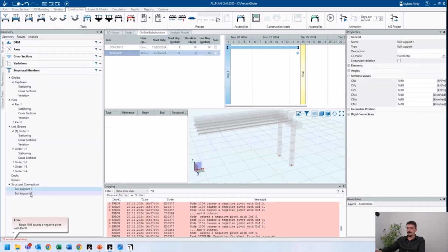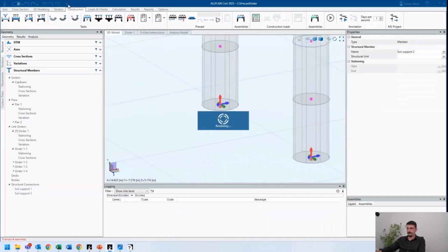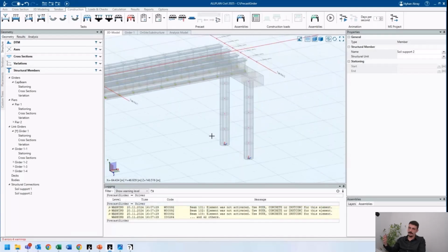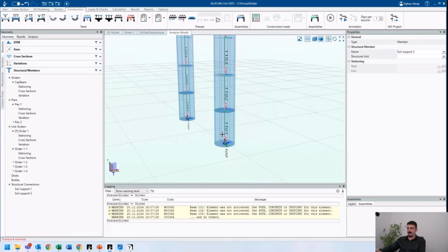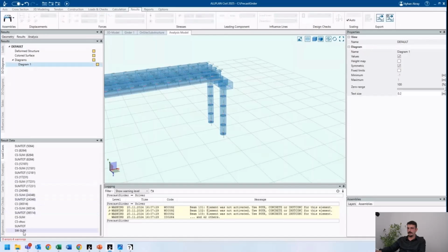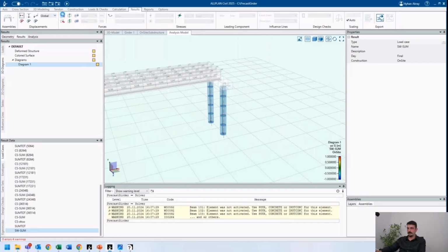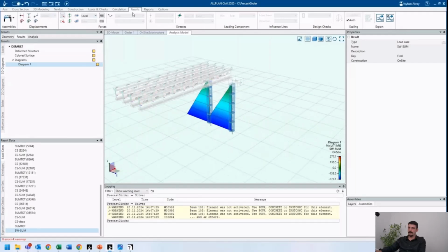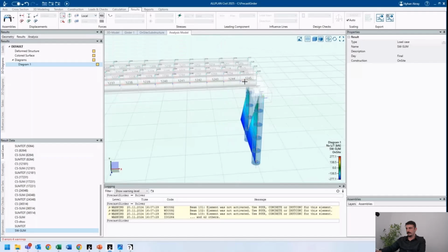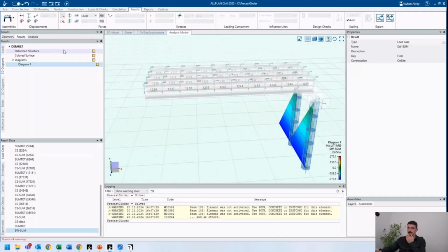I will activate them by using drag and drop again. I choose them with the control button or by holding the shift button. So all we are left with is the warning saying that there are still so many beam elements in the system. Please be careful to activate them or not. So all we have in the analysis model now is the piers. We can check from the results, and we can simulate their self-weight summations to see if they're activated or not. You can go to the results and the 3D diagrams and choose the load case to see if the axial forces diagram or the moment are activated or not. As you can see, not all the other members are activated, so we should activate them as well.